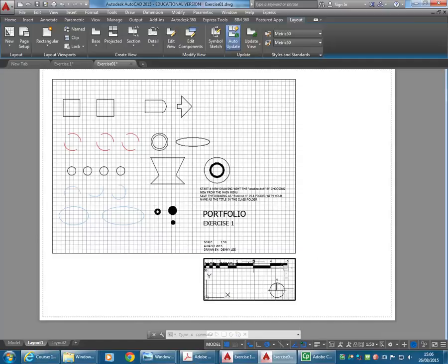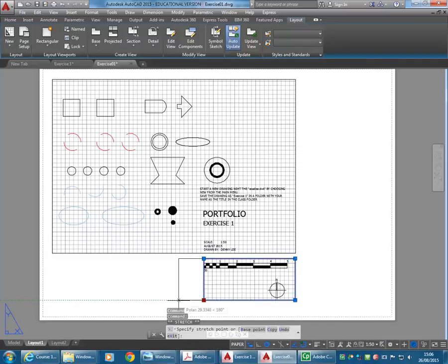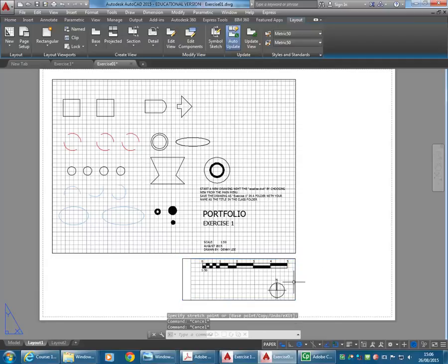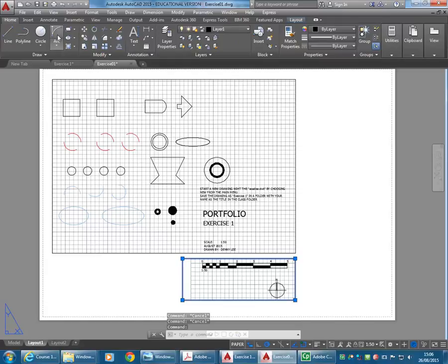So it's a bit small. The viewport's cutting off the left, so I'm going to click on model. That'll take me back to the page, so it says paper. So you're constantly switching back and forth, and now I can just stretch that viewport out to show everything. And I can even move the viewport. The normal commands work, so if I go and use move, I can just bring all of that down to the corner.